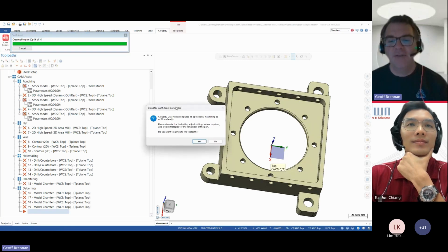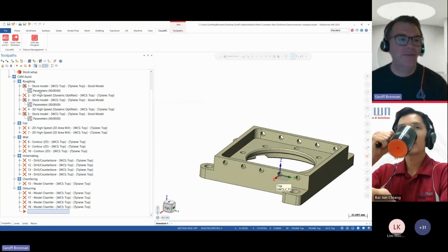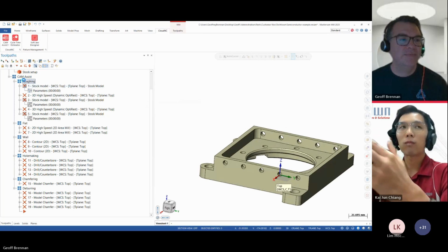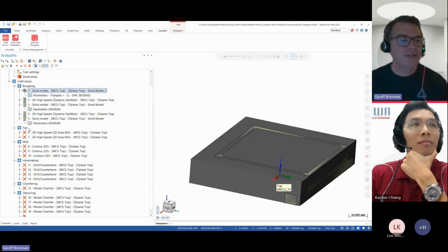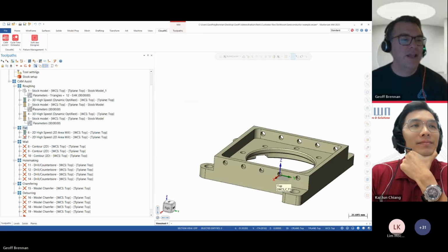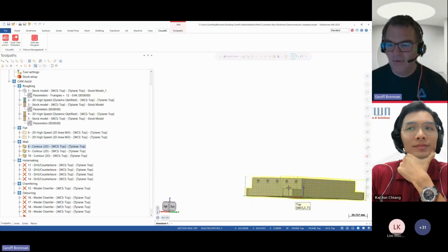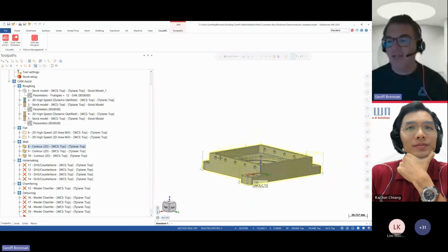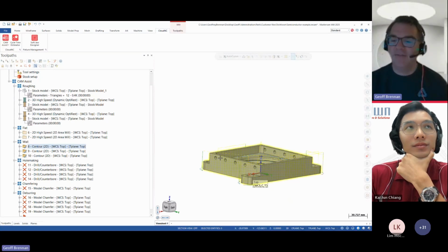If I say no here, I'm not going to generate the toolpaths in Mastercam, but then I can come in and check them one by one. Sometimes when you get dozens and dozens of toolpaths all at once, it helps to do it a bit more step by step. You can see here that I'm not going through the bottom to any great extent. So if I had my stock high enough above the vise, above my work holding, above my vacuum table, I'd be safe.